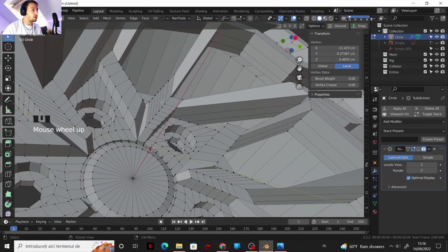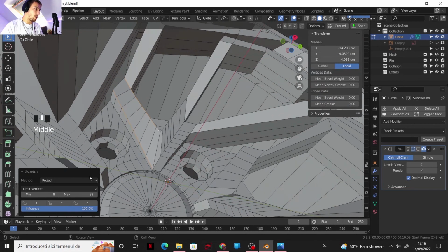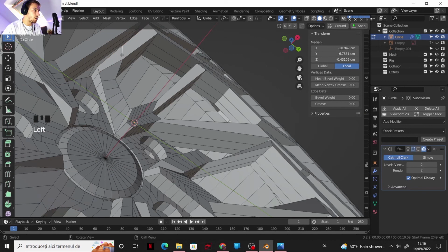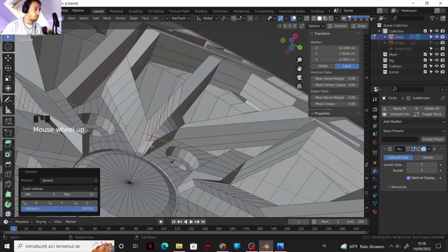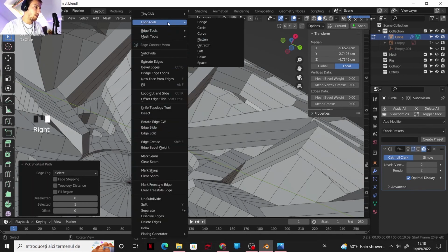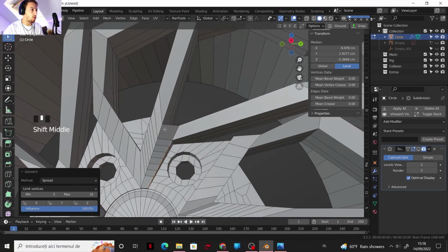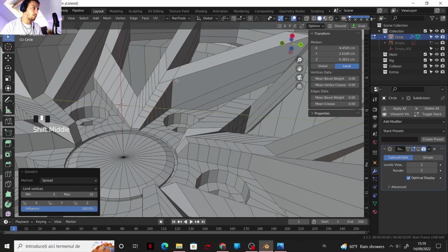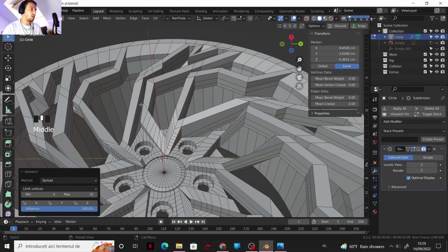So let's take a look. Now we are gonna use again a lot of G stretch. So G stretch, edge, G stretch. Okay, so that's the stretch needed here. Hopefully they didn't move too much. Okay, this looks pretty good. Now here I'm gonna need to adjust the slope, which is stretch. Okay, so now it's having a good shape. So that's a better shape. So I'm gonna do this for every spike, and I'm gonna come back.